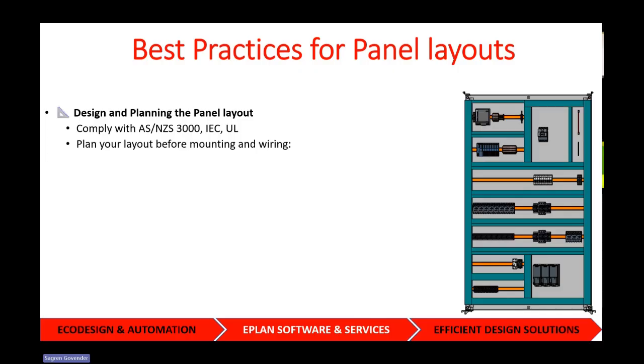Plan your layout before actually getting down to the shop floor, and of course the best place to start planning that is in EPLAN. Lay out your gear tray. It's easier to move things around on paper than to actually move it out in reality on the shop floor. So the whole saying is measure twice, cut once, and that is true with the panel layout. Place your devices, move things around, find the best flow and things like that before you actually start wiring.